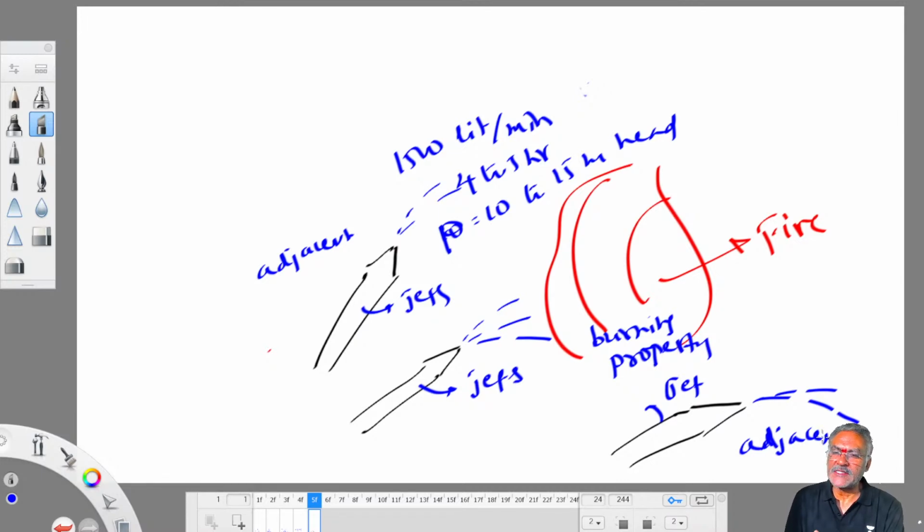So you have to keep aside 4 to 6 liters every day till a fire breaks out in a community. Once it happens, we can immediately drop that water and use it without compromising the other demands. That is how we meet fire demand along with other demands. We should not compromise on any other demand while serving the public. Every demand is very important. Then only it is a good, scientific system. I hope it is clear to you.